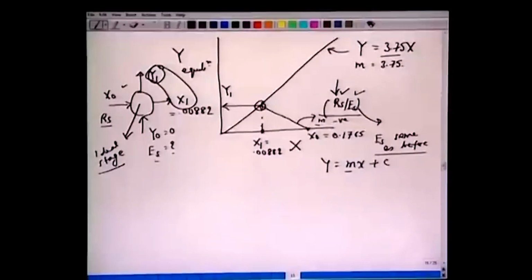You mark the slope, extend this till the equilibrium curve, and you will obtain y1, the mole fraction of exit concentration of this Es phase, the solvent phase. Okay. So, it does not matter whether graphically or by algebra; more important is trying to understand and mark what is happening in the stages here.